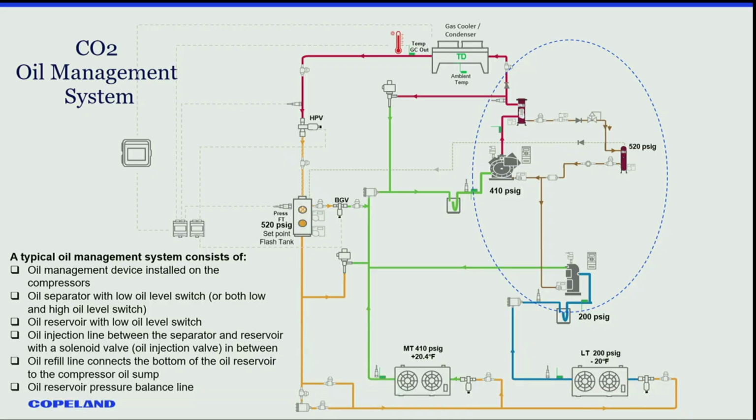And I've got another example that I could talk to. So we're going to talk about the oil system. Oil separator right at the outlet of my compressor, of course. I've got ball valves, solenoid valves, differential valves to help reduce that pressure. I'm feeding, in this particular example, through a cycle. I put a sight glass only because our unit has a sight glass. A filter dryer, super important, a large filter dryer, feeding both compressors.